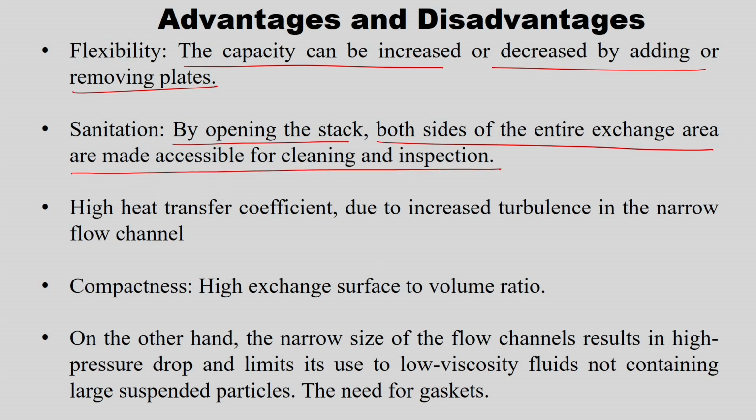It is just the plate in which the fluid is flowing, so I can remove the plate very easily and clean and inspect it when needed, right. So, sanitation wise it is very advantageous, and there is a high heat transfer coefficient due to increased turbulence in the narrow flow channel, that is the way the corrugations were made, and the heat exchange surface to volume ratio is very high. So, that is the way it is compact.